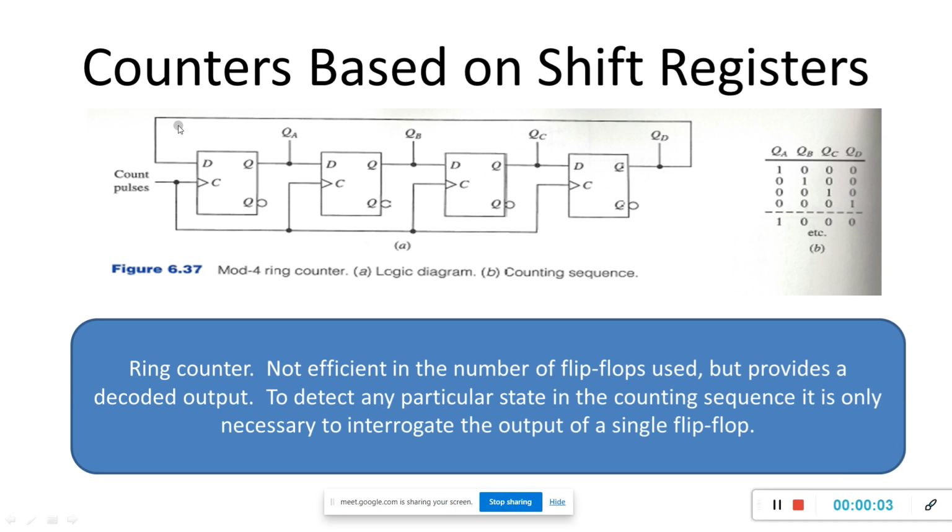Okay, so in today's class we are starting with counters based on shift registers. Before that, we have already studied counters. A counter is a pattern generator. It generates different pattern sequences. It may be a binary counter, it may be a non-binary counter, right? So here, we will be studying some of the counters based on shifting operations.